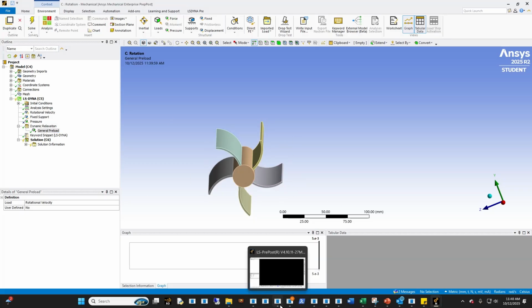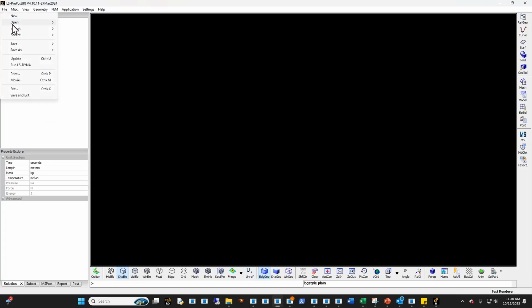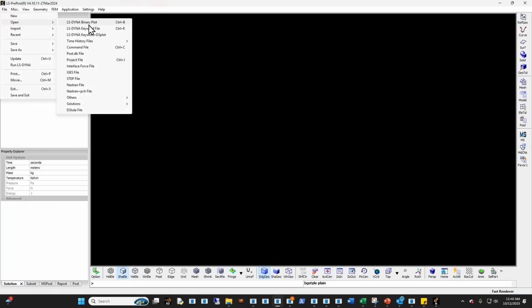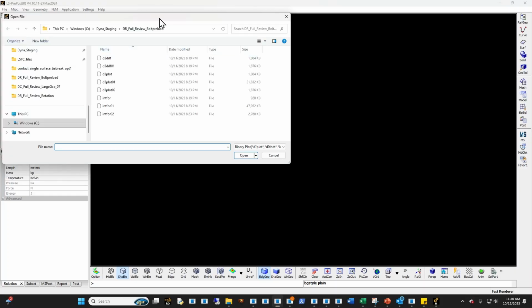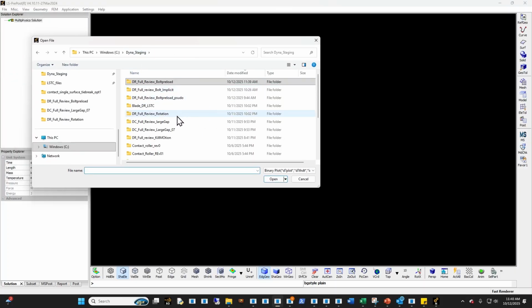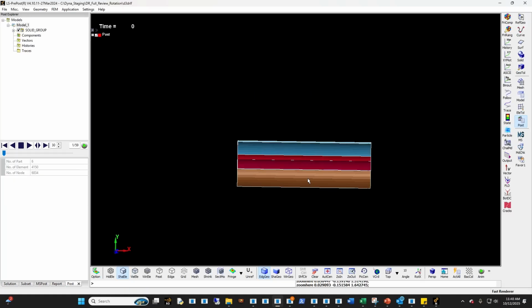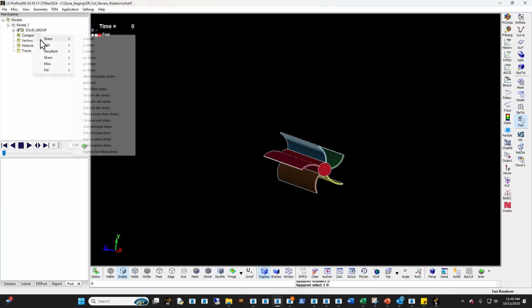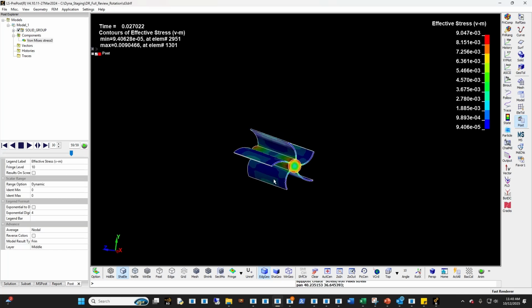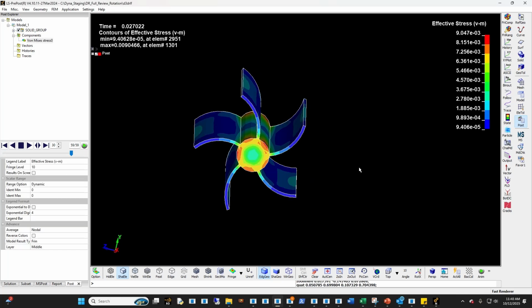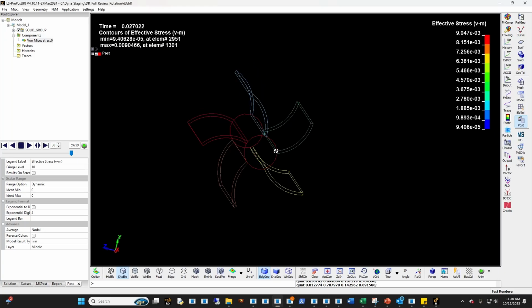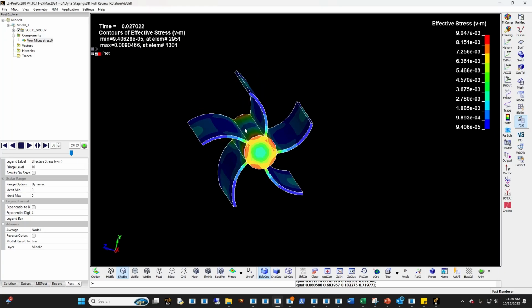And then what you see when you look at an analysis like this is that it's actually going to include... actually, let me show you this. Let's look at the rotations, and then if I just look at DRF, right, this is the dynamic relaxation database file, and if I just show the mean stress. Okay, this is the stress due to the rotating body. This is all inertial stress, right? As the body rotates, inertia is going to cause some stress on the rotating body.